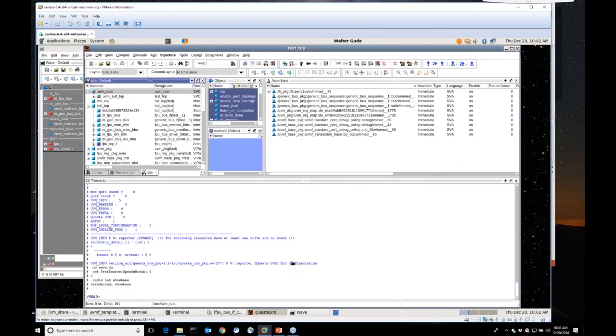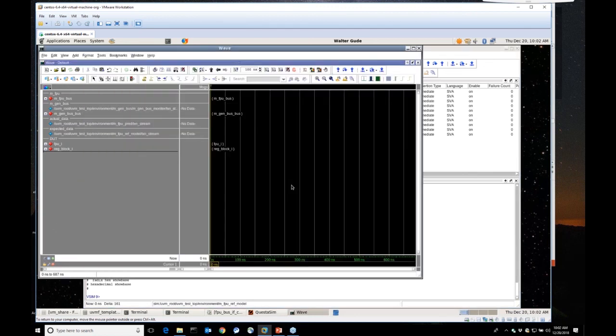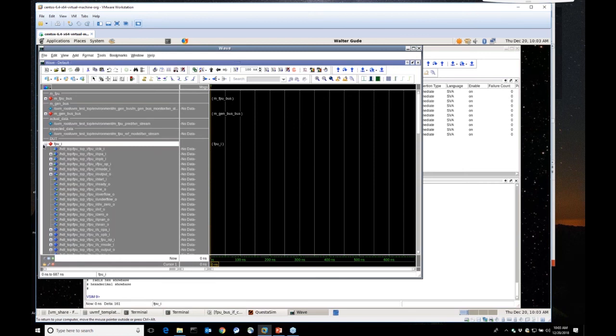So we'll see that I ran through the code generator. I did that make file. You'll see my entire environment has been generated. I've got my environment that has my FPU bus agent. It's got that generic agent. It's got my scoreboard. It's got the reference model that I instantiated. And you actually see over here that when I loaded this design up, it automatically added all the waves for all of my transactions and for my register block and all the I/O into and out of my FPU.